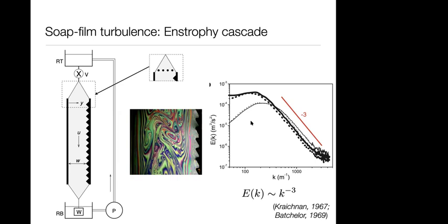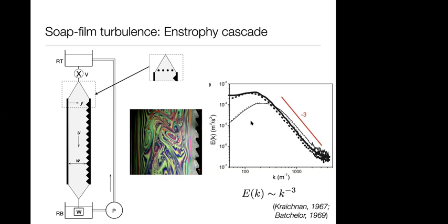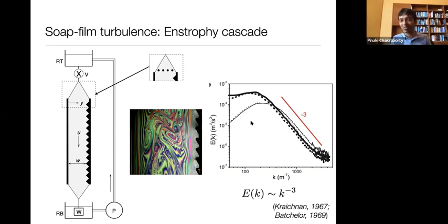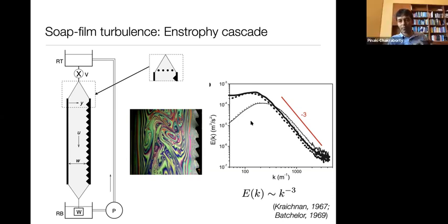Okay. So for example, in this experiment where you have a smooth wall on the left and the rough wall on the right, you're saying if you want to predict the drag for the smooth wall, then go close to the smooth wall, and for the rough wall, go close to the rough wall. Precisely, yes. Okay. Thank you. Sure. But how close is something that is still iffy. But you emphasize it should be outside the viscous layer. Absolutely, yes. Thank you.